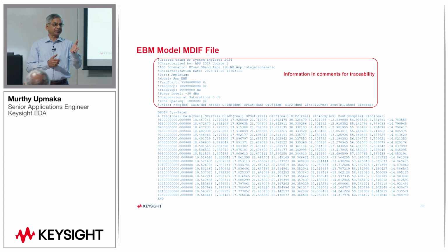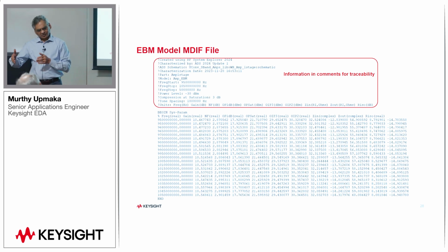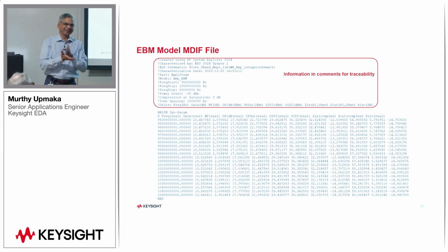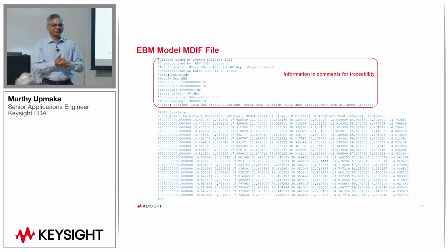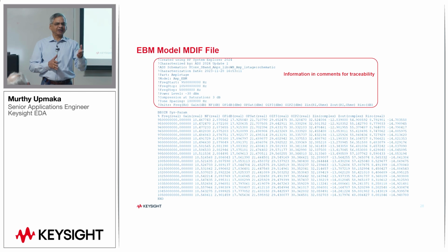But we do have solutions for that. One solution is X parameters. If you extract X parameters as a function of load, that becomes the best model for the amplifier sitting in here. So again, there are so many ways to cut this amplifier modeling, which can be a whole day discussion. Last year, we also introduced what we call dynamic gain amplifier modeling. If you search the literature, DGA is already there.